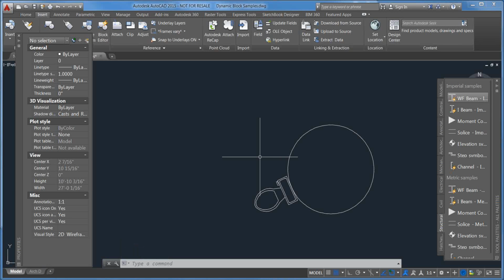Many of you know who Brian Haley is here, our Civil 3D expert. He was working on a dynamic block for civil parts, and I believe what he did was lock the text to a line and then constrain the line to be horizontal. He was able to move the line around dynamically and rotate it, but the text was locked to be horizontal. So it takes a little trickery, perhaps you might say. You kind of have to experiment with some of those features.